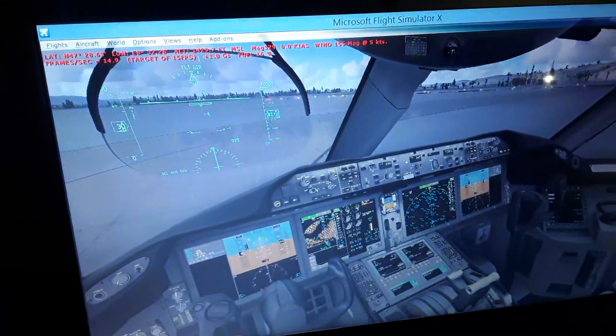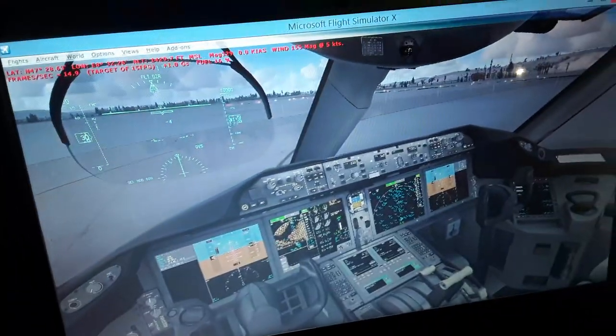We're going to have to select from the flight management computer in a couple of minutes. I will show you how to use the flight management computer to create a flight plan or a flight path or a route for use with this navigation display, and how you can interact with the autopilot flight director system panel. You can connect the LNAV and the VNAV navigation, which will use the flight plan you have created to follow as a flight path. So you can see.